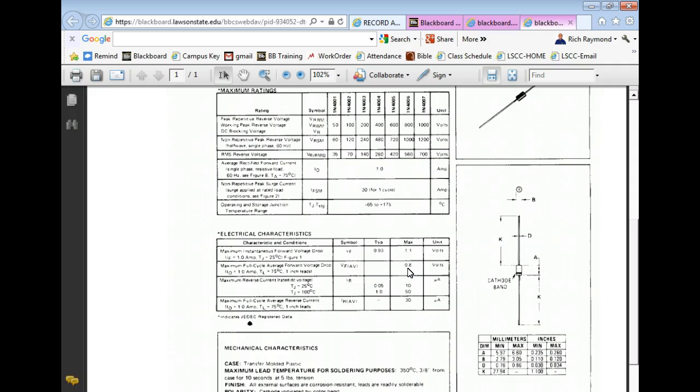So see, just reading these things, we get a pretty good feel of what we're going to be talking about, right? Y'all understand that? Okay. Now, of course, we're doing the lab. The lab's going to be hard, so you don't have to have data sheets. But understanding how to read the data sheet, right off the bat, I know I can replace a 4001 with a 4003, but I couldn't go down, right?